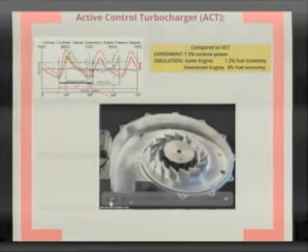So that's what I do. I will oscillate that vane at the same frequency, and whatever amplitude I come up with, to follow the pulse. We call that active flow control. It doesn't need external power. You might do it passively. Let the flow open the vane and close the vane against a spring either way. You could do that too. We call that passive flow control. Two patents on the matter.